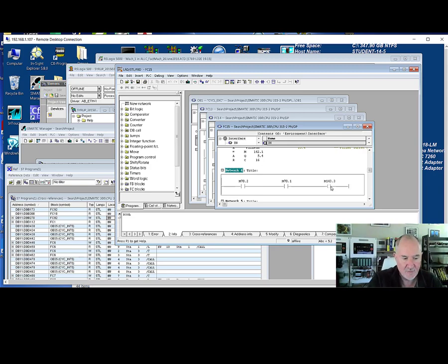If either one of these bits, M70.2 or M70.1, did not come on, then neither would M143.3, and that of course would also mean that Q5.4 did not come on. So I don't know if you can see my screen here, but this is the little notepad that I have, and I have a trace of everything that I've been looking for. Just for fun, we will trace this one further.